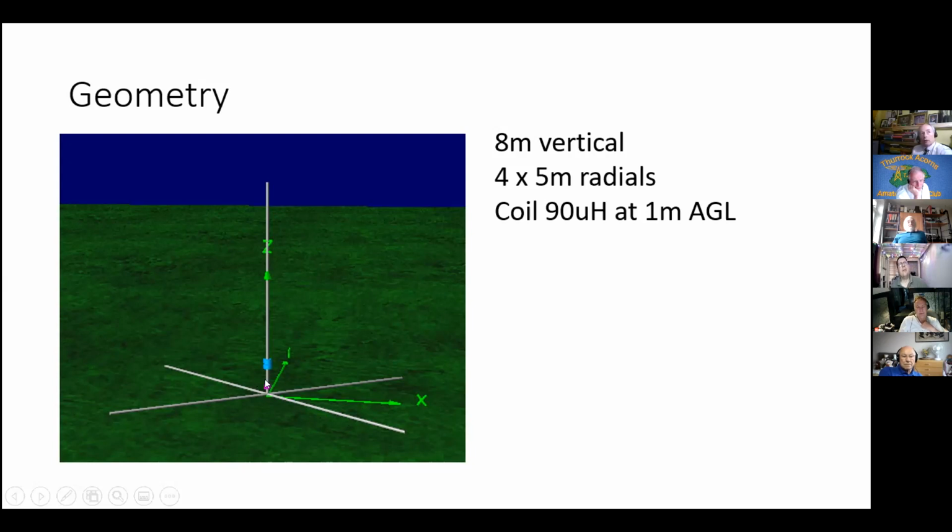There's a spike in the ground, a fiberglass pole over the spike, and the loading coil is about 1 meter up the antenna so that it doesn't have a metal spike through the middle, which might not make it work any better. And the feed point is a little bit below the coil, which works out at 90 microhenries to get it resonant at the top end of the 160 meter band. I let the ATU drag it down to whatever frequency in the band I want, because my ATU is an ex-military one that basically likes electrically short antennas only.